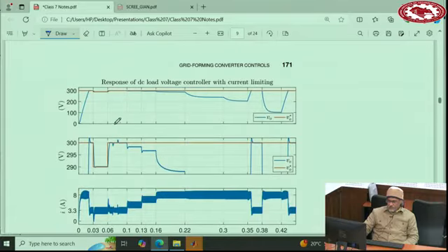Okay, so this is the starting transient when the output voltage is 0, and then it takes some time to go up. During this time that it is going up, if you look at that, it linearly goes up because the current is limited. So it's exactly 8 amperes going to the capacitor, and then the voltage keeps going up linearly. Once it reaches there, the current comes back to the rated 3.3.